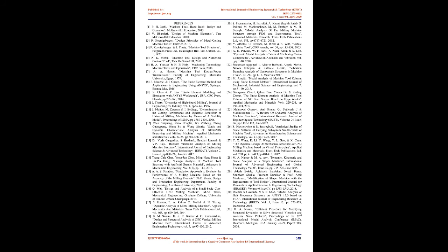Summary. The virtual design was carried out for mechanical redesign of Egyptian-made milling machines for modification and updating by using CAD. This is done by using a set of commercial packages like Ansys and Solidworks beside Gearlab and tailored codes written in VB6 for calculating the cutting forces and required power, as well as codes to design main and feed gearboxes. This technique has several advantages as indicated below.